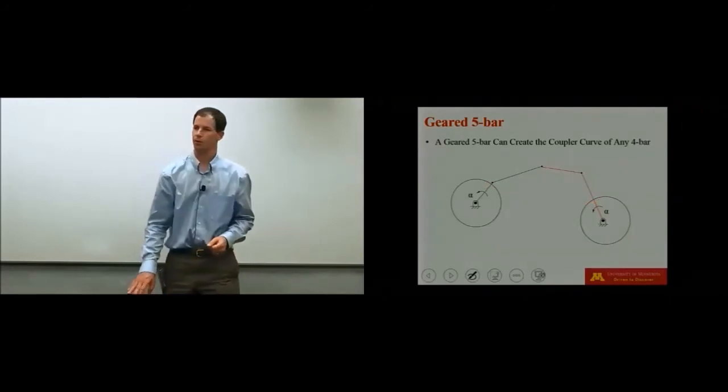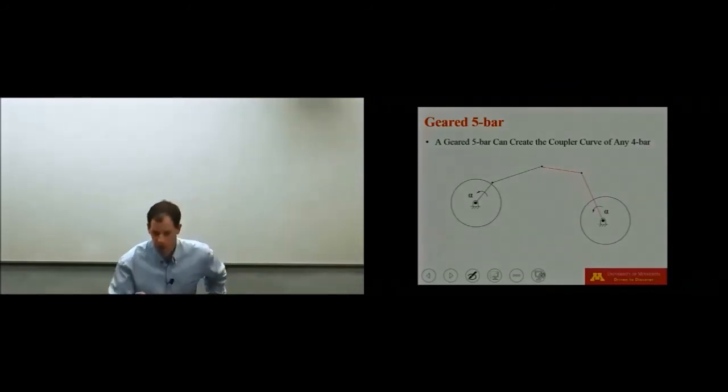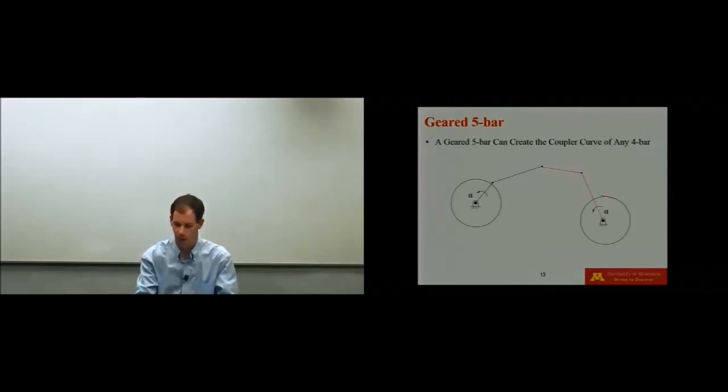Another option, you might say, well, you're doing one-to-one velocity. Why stick that idler gear in there? So one alternative is that I can just create a belt drive, something like this, where I would create maybe a timing belt between the two of them, something like a cog belt, so I don't have slippage. But it just replaces the fact that before I had a gear, and gears are a little more expensive to create and get the center-to-center distance just right. Now I can just put a belt in there and get that same effect. And so now I have a belt-driven 5-bar mechanism. And again, now these sheaves right here, the belt, would be rigidly connected to these two links pinned to ground.